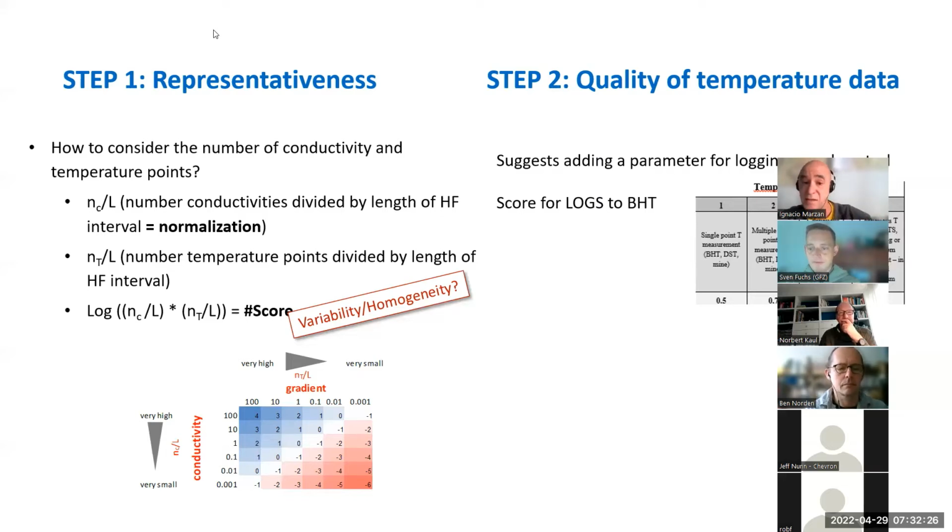The normal ones in multi-probes usually have only 0.5 or 0.1 degrees precision. So that means our probe cannot take a continuous record, but is much more precise than the one that my colleagues from hydrology are using, with temperature sensors that are not precise enough, especially for boreholes of less than 200 meters depth.